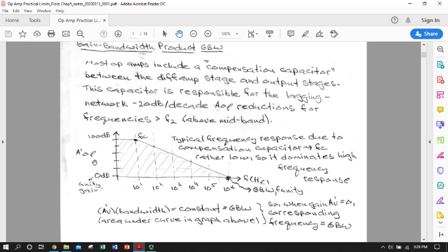So we're back to open loop now. No negative feedback network. So if we were to look at this graph starting over here on the left-hand side, we have a mid-band region where, this is open loop, so we've got crazy high gains, 100 decibel gains up in the mid-band. And then we will hit the upper extent of that, our upper critical frequency, also known as F2.